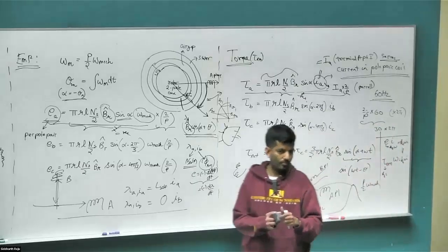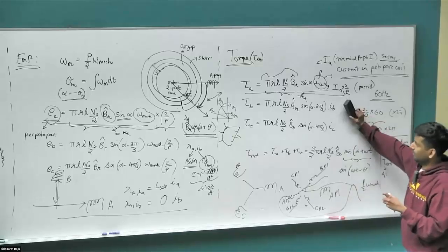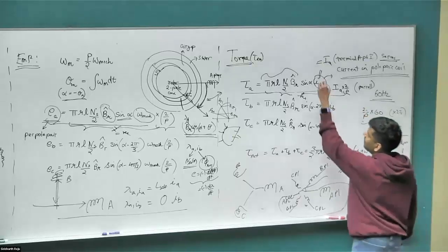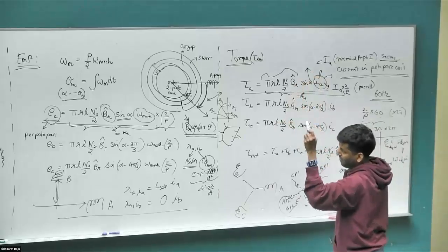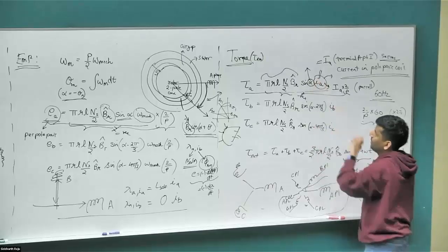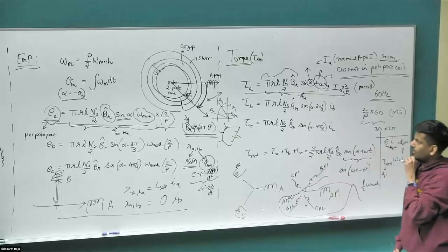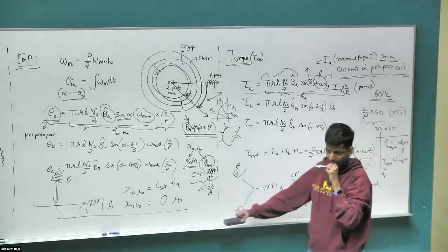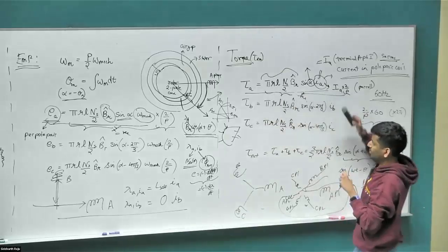Any other questions? Okay. So let's go back to our torque expression right here. This alpha is basically our mechanical rotation scaled by a factor of P by 2, right? And if the rotor is not rotating, that alpha is going to be a fixed term. What is going to be a torque? Will there be a torque if I just pass a current through the A-phase winding?